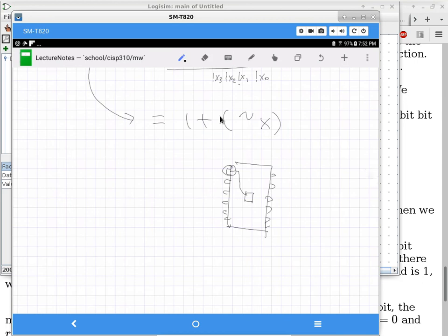So you have a conductor that is kind of short, probably measuring in multiple millimeters, 5, 10 millimeters or something like that. But nonetheless, it is a wire. And it's a wire that is floating, which means nobody is telling this wire whether it should be high or low voltage. It's just what we call floating.